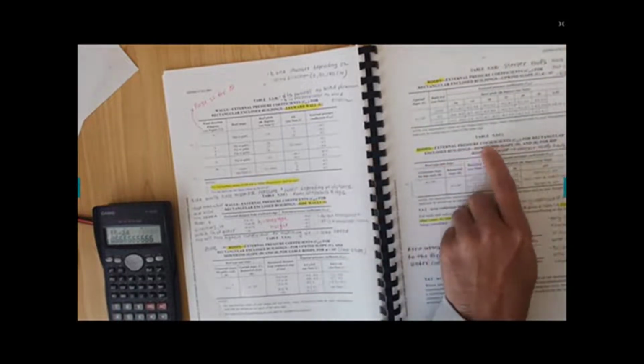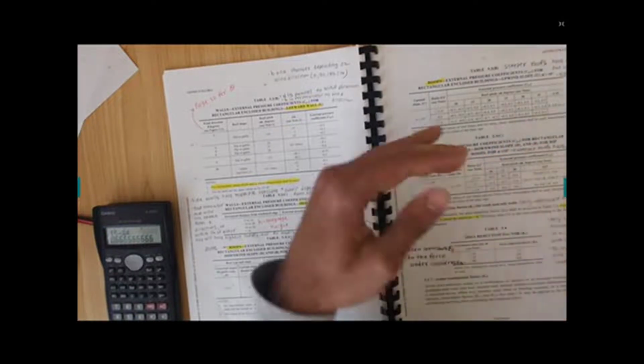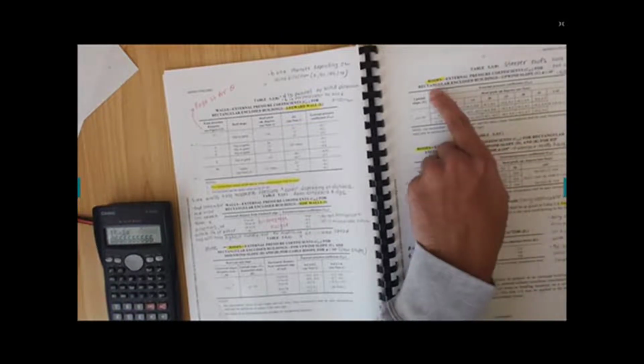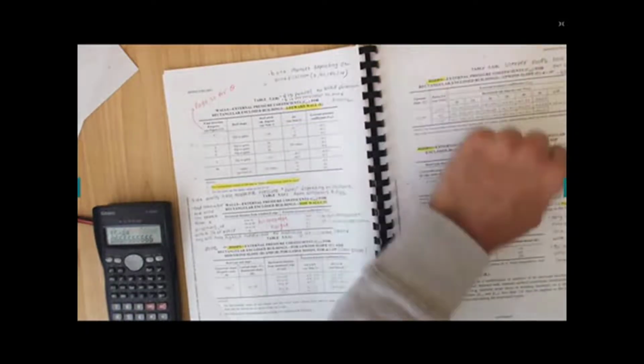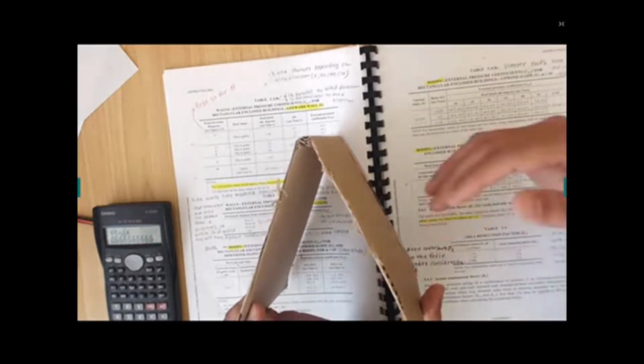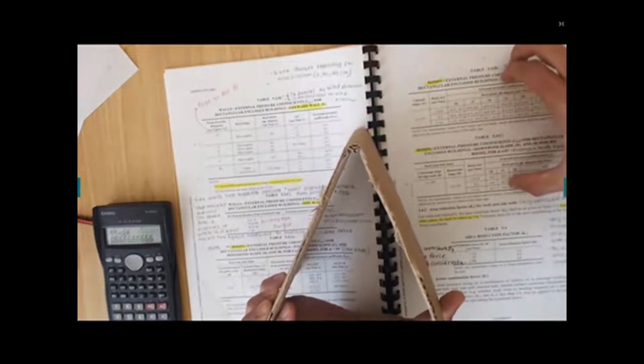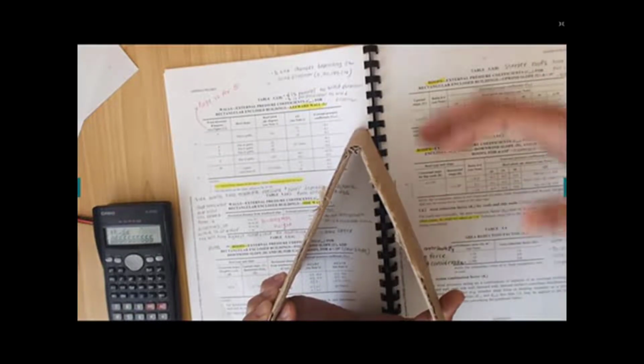Again, this is a steep roof. And what is the difference? External pressure coefficient for rectangular enclosed building, downward slope, and for hip roof. So if you are talking about downward slope and alpha greater than 0, you can use this one. And this is up. So between this and this, these are used for alpha greater than 10. These 2 tables can be used for alpha greater than 10, and they talk about whether you want to calculate up or down when the wind is coming here. So they have given you 2 tables for alpha greater than 10, with the up and down.